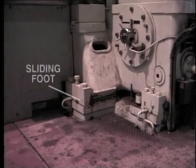In this case, the rotor contracts much more rapidly than the shell, and as a consequence will reduce the differential expansion and generally move into the negative zone. Normally, the manufacturer sets limits of differential expansion for both the negative and positive sides. The expansion position of the governor pedestal is also indicated. After a short overnight shutdown, it is probable that the turbine shell will still be considerably expanded, while the rotor has contracted to provide a negative differential. This indicates that a hot start is required. Please make sure to check the manufacturer's recommendation for your particular machine.